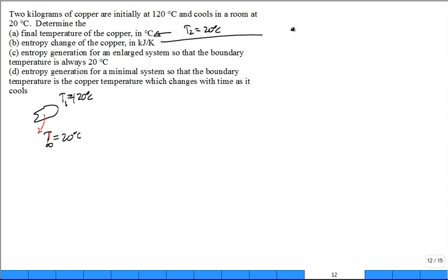Sometimes you calculate entropy change by just knowing that it's a property, and so it's mass, specific heat, natural log, T2 over T1. Remember, it is a property. So if you know the end states, you can get the change in the property just by that characteristic, not worrying about the balance or what happened. That's not the same as equation 6.13, because it has C times the natural log of T2.